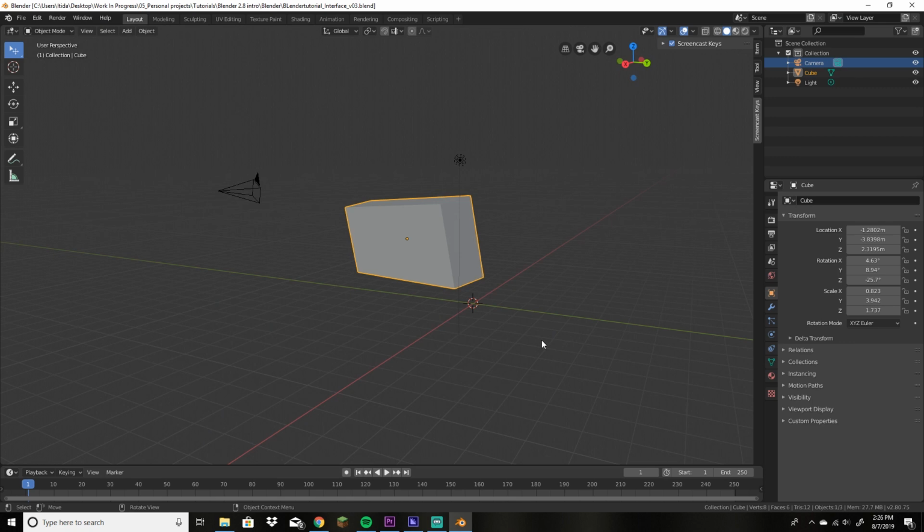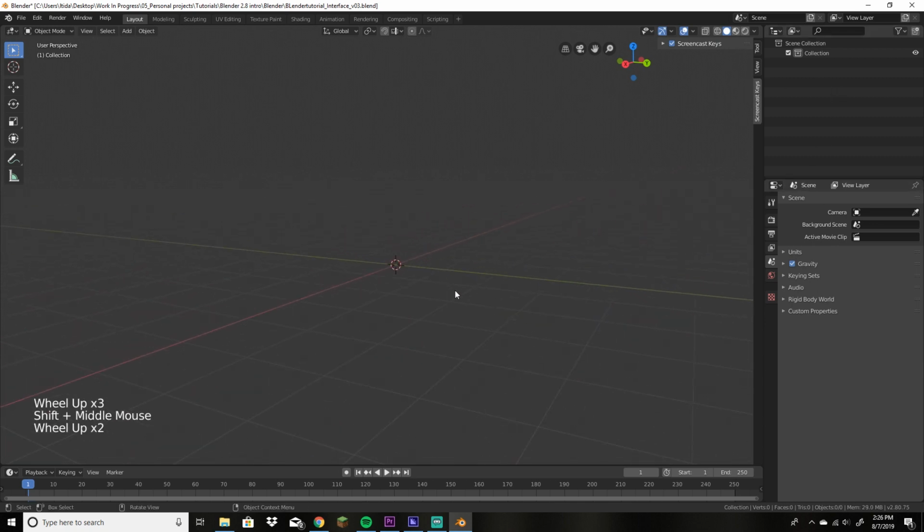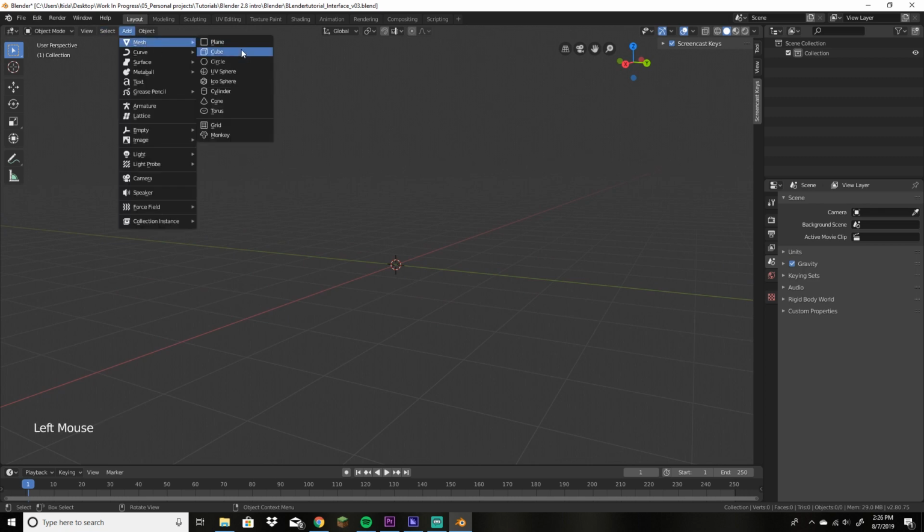In this part, we're going to be focusing on creating the balloon and the bucket that we're going to be using in our scene. So first, we're not going to need the camera or the light or any of these. So just go to your box select tool, select them all, and hit X to delete them. Also, the 3D cursor that I moved in this last section, I'm going to snap that back to center by hitting Shift S and cursor to world origin. So to get started, just center up on the screen, and let's add a UV sphere.